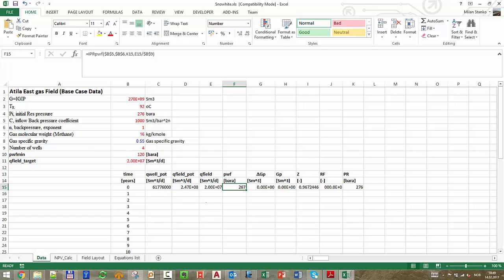Yes? So from there we can calculate delta GP. Delta GP will be the rate, this rate, right? This rate times, remember, to calculate the reservoir pressure, you need the rate of everything that is draining out of the same container. And all of that is all wells, okay? Is the rate of the field. Times, I will make it general, so I will say times this year minus this year, okay?